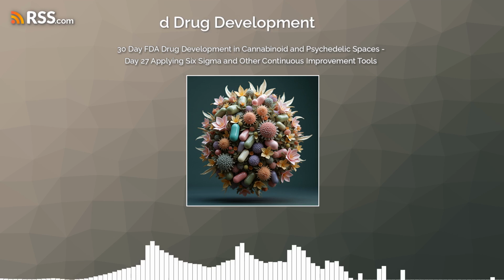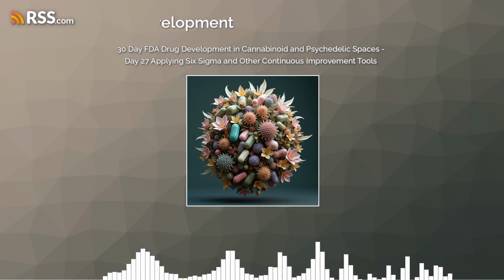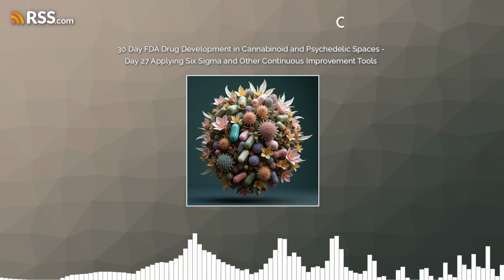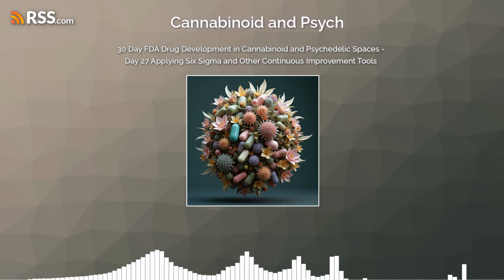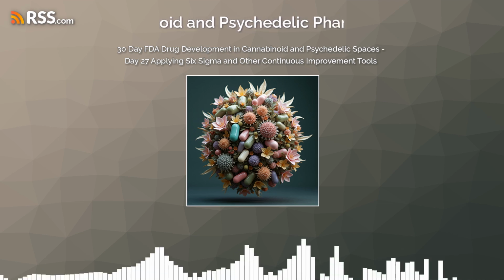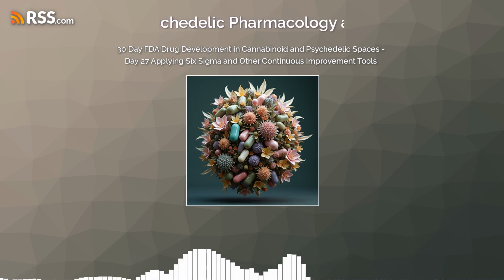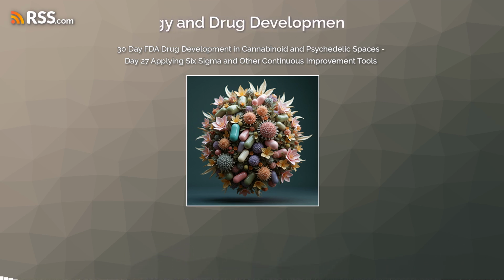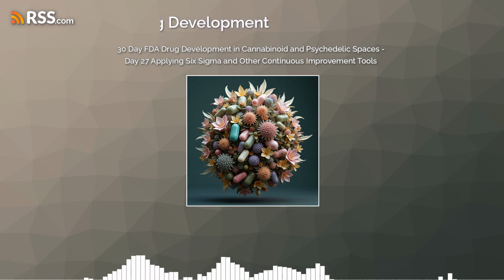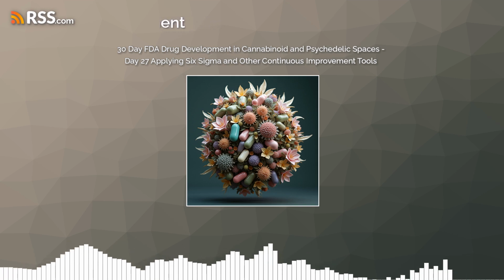Right. So we talked about things like failure mode and effects analysis. That's one tool that can be used. And it's really about identifying those potential failure points and then assessing, okay, if this goes wrong, what's the impact going to be? And that allows you to prioritize so you can say, right, these are the areas we really need to focus on. These are the areas where we need to put safeguards in place. So you're building that safety net like we were talking about before.